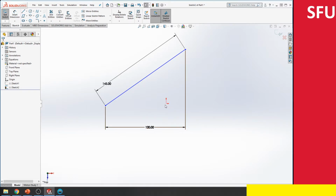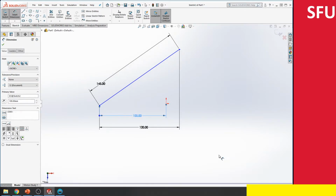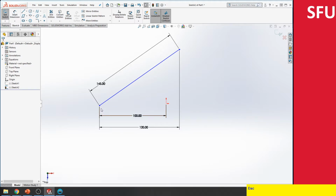But I can basically set the distance of this point from the origin over here. So the way I would do it is click on the smart dimension again, click on this point and this point, and then again I can basically do a horizontal. There isn't really a vertical constraint. There is. It's a very small vertical distance. Right now I can just do the horizontal constraint and just set this to 100. So it moves all of the entities corresponding to it. So now the only thing I can do is move the point vertically.